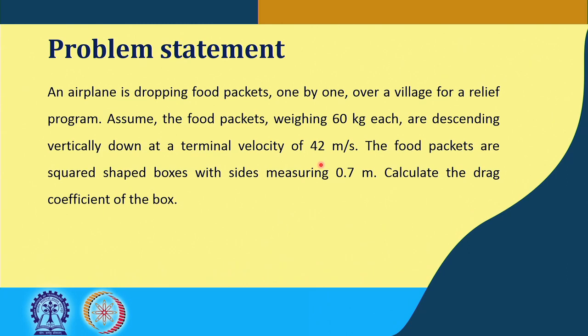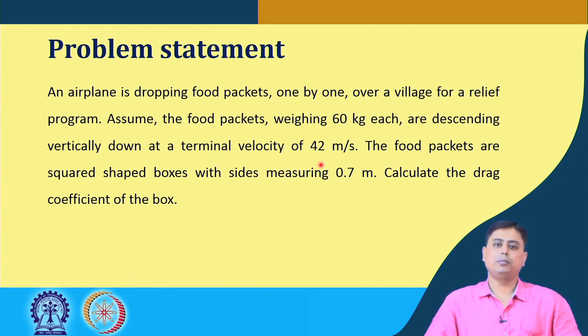So, what happens when a particle is dropped in a pool of liquid? Its velocity accelerates to a certain velocity, and after a certain time the forces acting on it and the gravitational force all balance, and then the particle does not accelerate anymore. It then falls at a constant velocity.